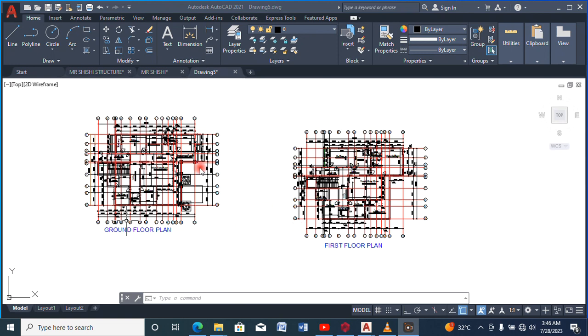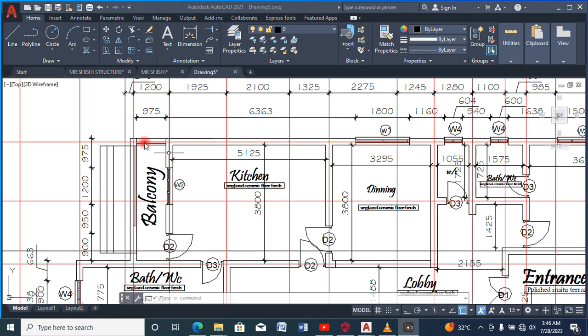There are basic principles on which CivilSoft works. CivilSoft understands only your rectangle as a tool used in designing your slab, your circle as a tool for designing your columns, and your line. Anything line, the software will understand as a beam.